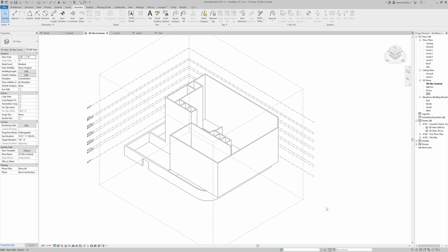So the next step I take after I have all my walls modeled is to start modeling some of the floors. And you can see here all of my walls are either 2 feet or 1 foot generic walls. I don't have any curtain walls or windows. I'm just denoting them as placeholders where these would go.